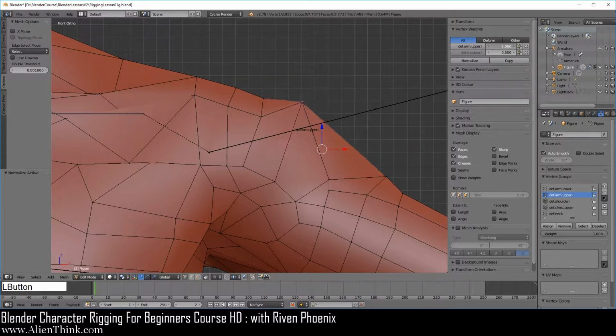So Blender doesn't care what you do over here. This is for you, so you can position the vertex just like what you want. Now if you want to see the actual numbers, you simply have to click on normalize. So it's good practice that once you've changed these numbers to position the vertex exactly where you want, you simply click on normalize. It's actually a pretty straightforward concept as to how this is working.